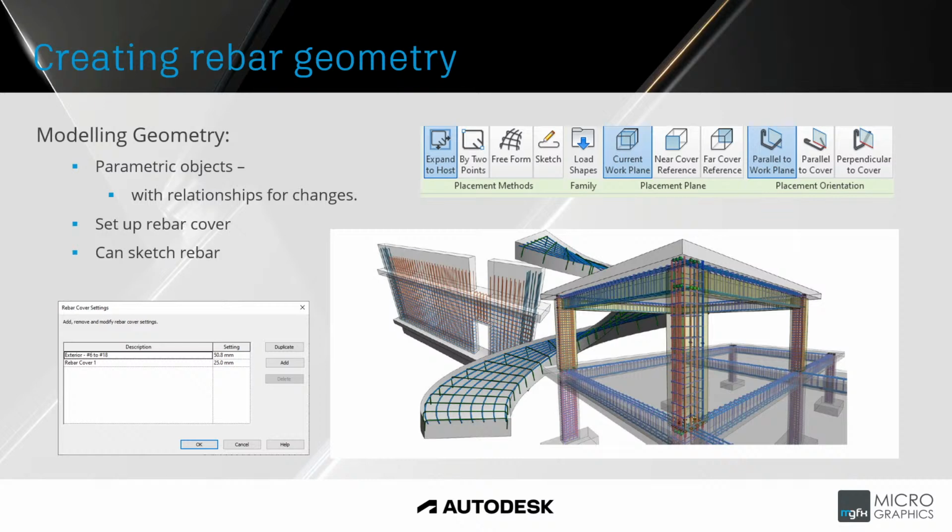You can also do in-place families in the full version of Revit, where the shapes can be very complex, meaning you can have concrete structures that are very complex. Now, that's just the modeling, but within that, your rebar lives as a parametric object. So if a change happens within the concrete model, be it the column changes height or size, then the rebar adjusts according to the dimensions of the structural item.